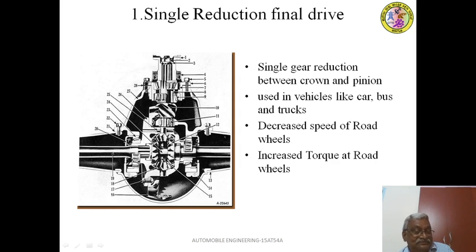While they are spinning, they walk over the right side sun gear teeth, and now this pinion has two movements. One is around the shaft due to ring gear rotation, and another one is due to spinning of the planetary pinions.